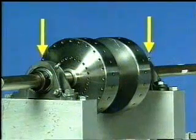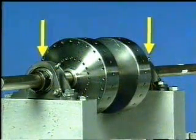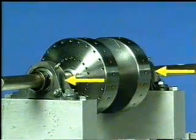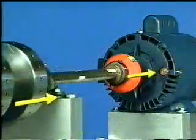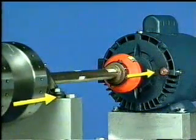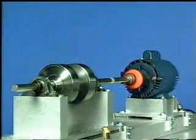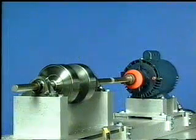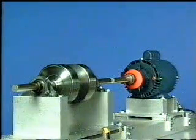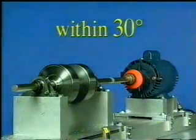Therefore, phase readings in the vertical direction from one end of the component to the other will be in phase. The horizontal readings on the component should also be in phase. And axial readings across the coupling should be in phase. As a rule of thumb, when diagnosing machinery conditions, most actual machinery phase measurements will not be exactly in phase or exactly out of phase, but should be within 30 degrees.